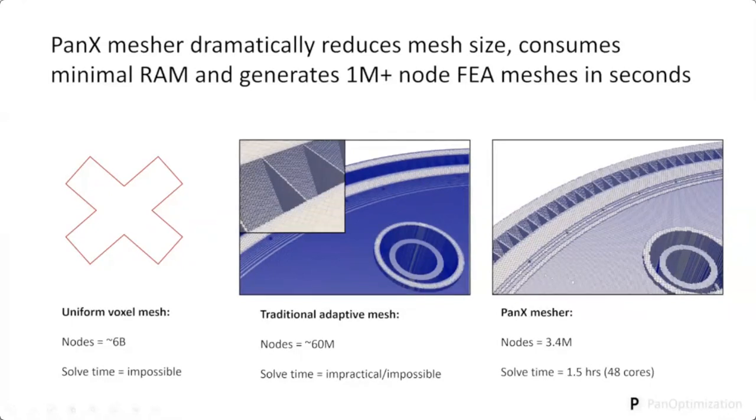So that brings us to our meshing approach, and we refer to it as feature-aware meshing. What it's really doing is a very efficient search of the geometry before generating the mesh and essentially flagging different things. So it can say, this is a thin wall, this is a thick wall, this is a small hole, this is a big hole. And we're now completely relieved of that small voxel discretization requirement.